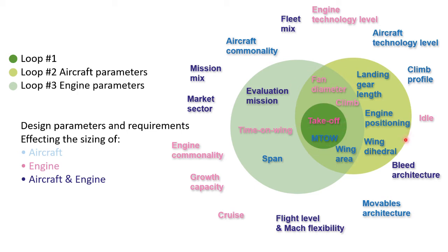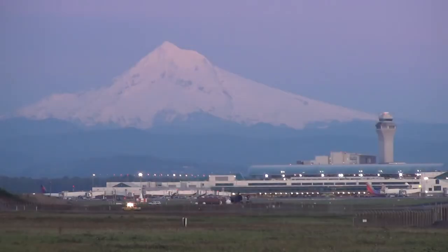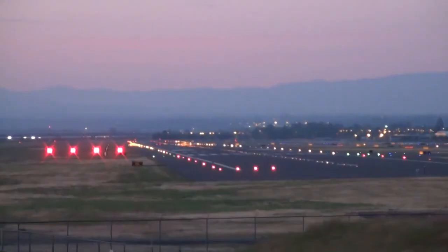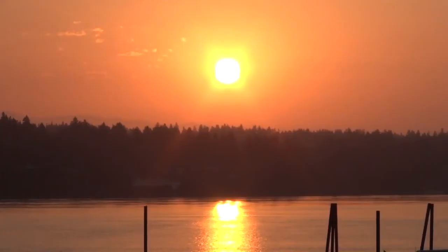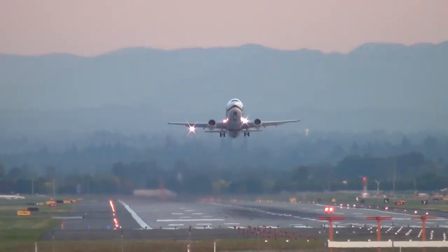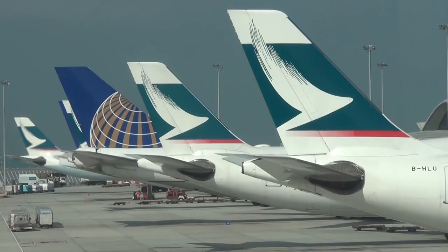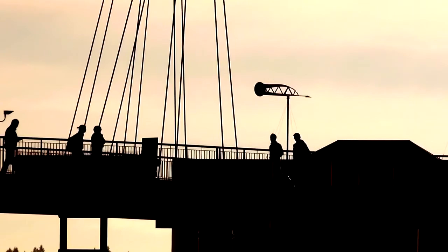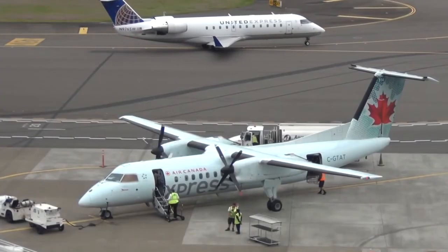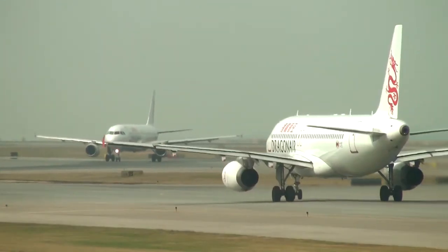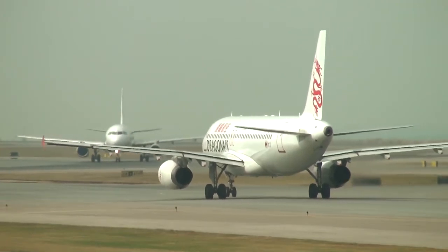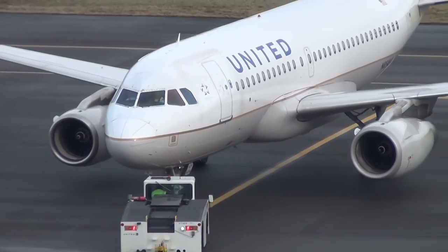This pre-development phase usually takes around a year, but can last longer for a completely new aircraft model. The aim is to finalize a robust engine, nacelle, and integration concept before agreeing a development plan, which includes design, testing, verification, validation, and maturity. Both the engine and nacelle manufacturers make commitments on key performance and economic elements, enabling the aircraft manufacturer to provide all aircraft guarantees to its customers. This process is similar for both a completely new aircraft engine configuration and a new engine option developed for existing aircraft.